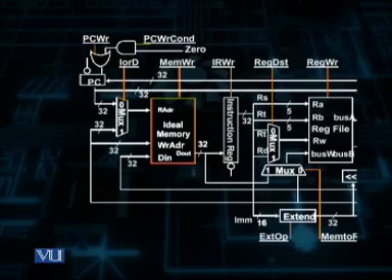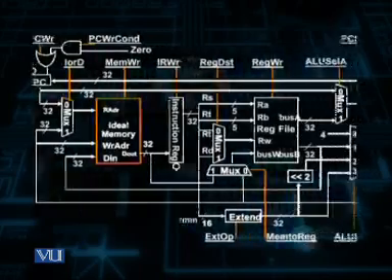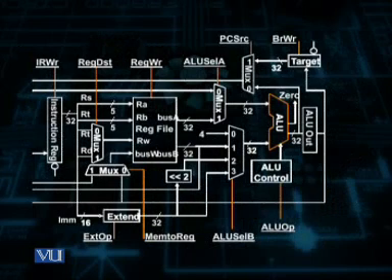Secondly, the select input ALU select A to multiplexer 3 is made equal to 0. ALU select B to multiplexer 5 is made equal to 0, 0. Here you can notice that the multiplexer MUX5 is a 4:1 multiplexer. Therefore, a 2-bit code is required at its select input, and for this purpose, this select input is equal to 0, 0.